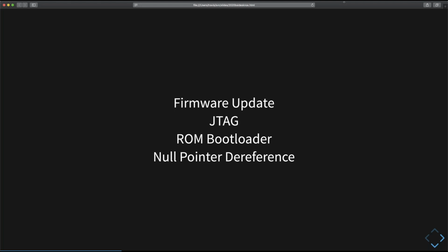Yeah. For Bluetooth, you don't have to do chip extraction. For Bluetooth devices in particular, Android has excellent support for logging Bluetooth to disk, which you can then replay in Wireshark in order to capture the firmware update as it goes over the air.